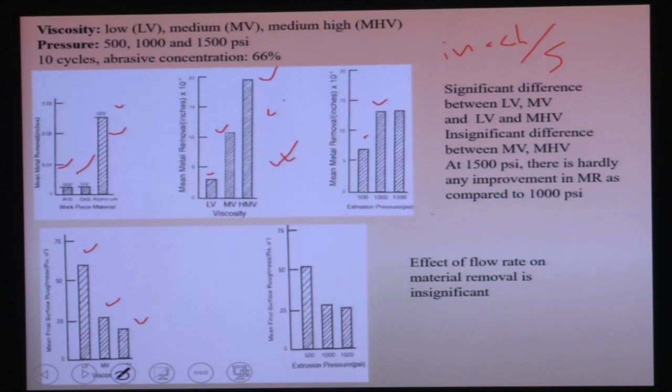Okay. So now if you want to do machine polishing on a harder material, obviously we shall go for a higher viscosity of this media. And when we are polishing softer material like brass and aluminum, then we shall go for lower viscosity of this media.